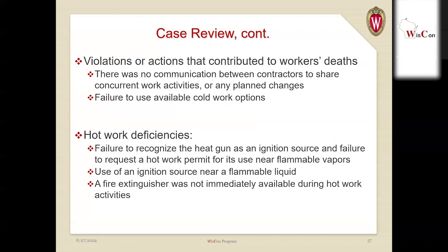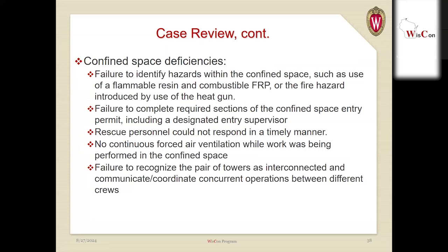So again, having that hot work elements all configured would have been super beneficial. Other confined space deficiencies were failure to identify hazards within the confined space, such as the use of that flammable resin and that combustible material that was being used, or the fire hazard introduced by the use of that heat gun.